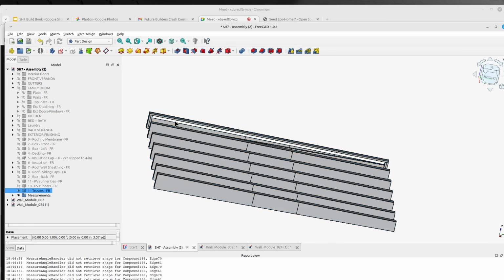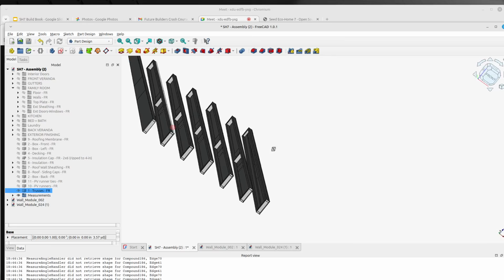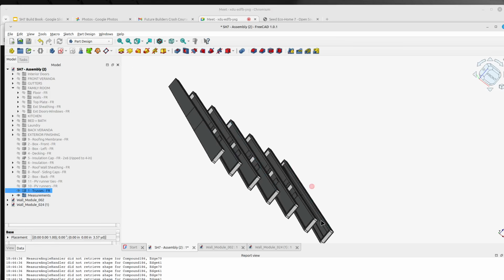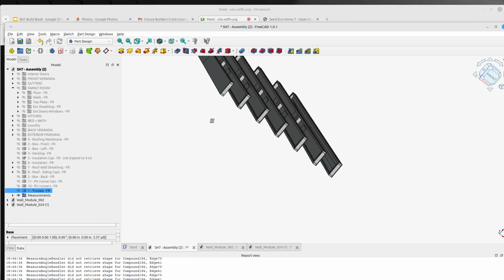There's a reinforcement on the top and on the bottom because it's a nailing surface for additions. For example, if the other section of the house is nailed to that, you have these nailing boards in this truss, these long 2x4s, so that you have a solid structure to bond the two home sections together.